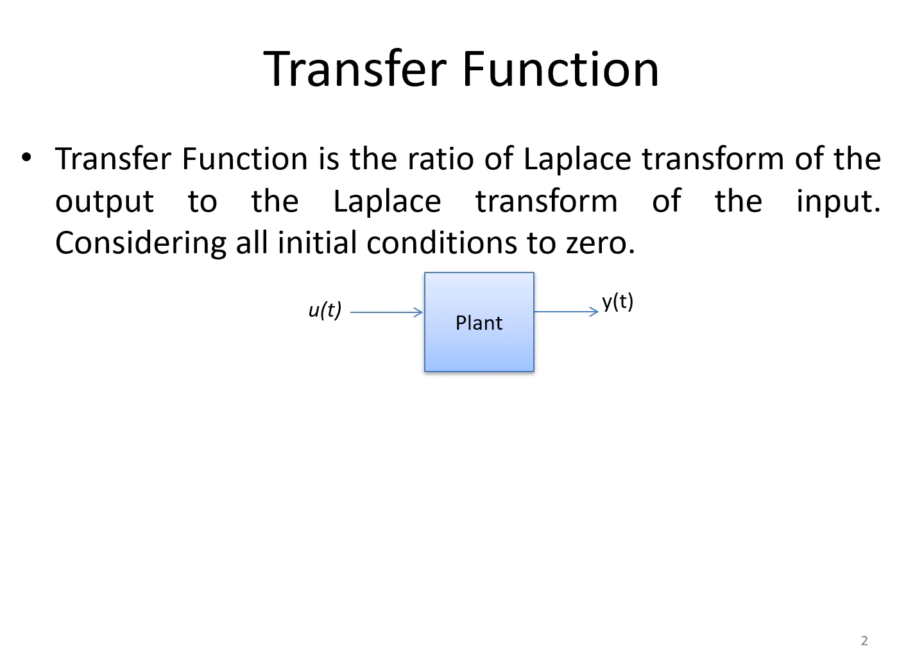A transfer function, as shown here, is a ratio of the Laplace transform of the output to the Laplace transform of the input, if you are analyzing your system in the S domain. For example, if I am analyzing my system response in the Z domain, then it is the Z transform of the output to the Z transform of the input.